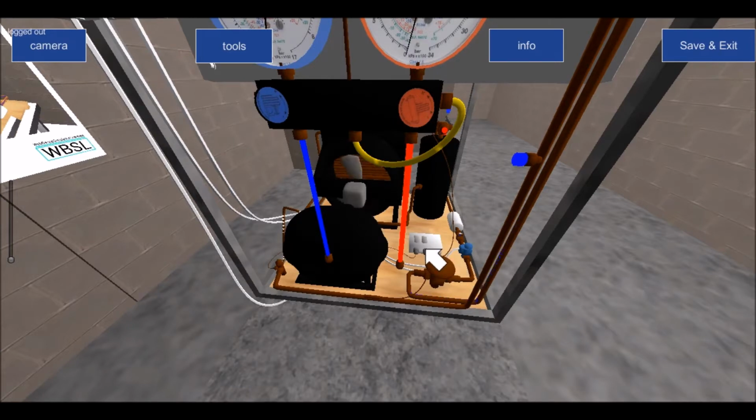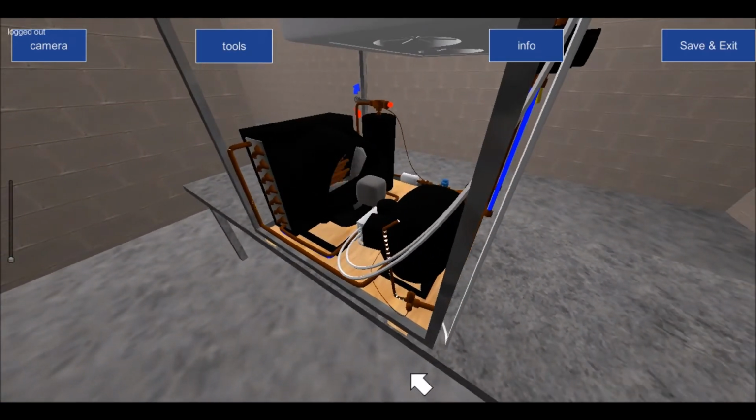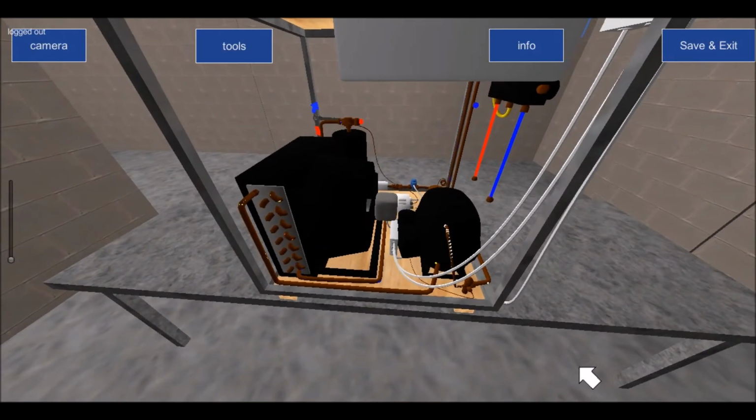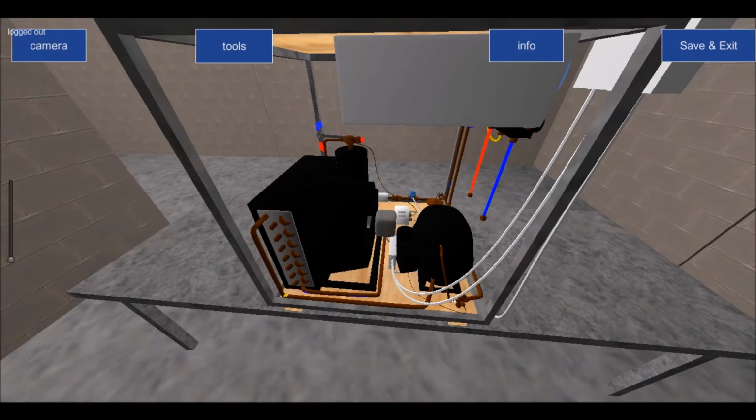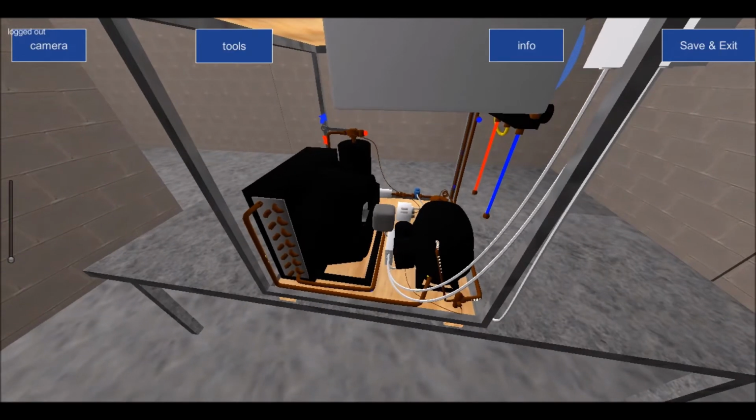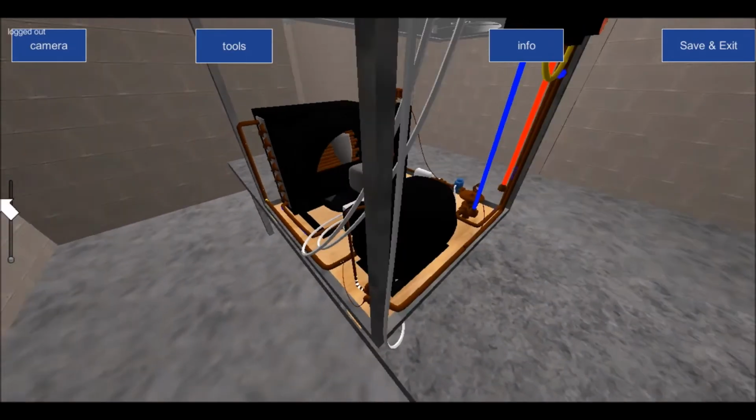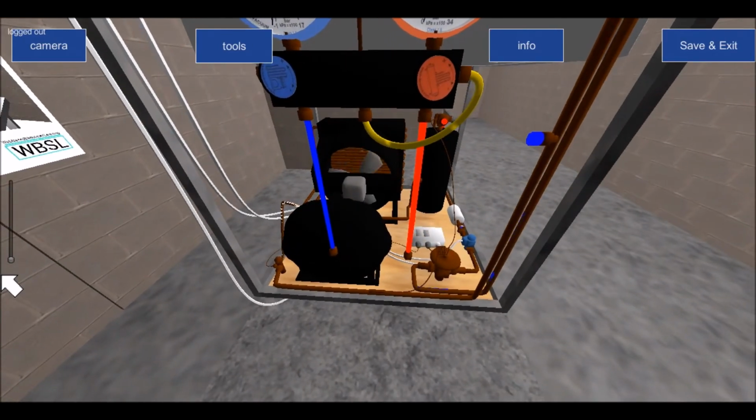Whereas the low side, again, you can see where the capillary is here on the suction side, so it's getting a low side reading. And again, the low side pressure switch is there for two reasons. One, for safety, or the second one is to cycle the compressor on and off when there's a solenoid fitted and you're trying to use a pump down.